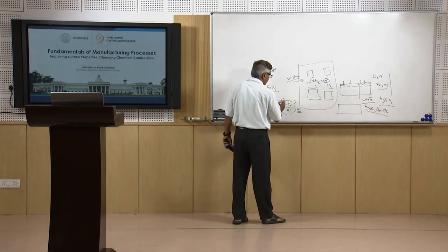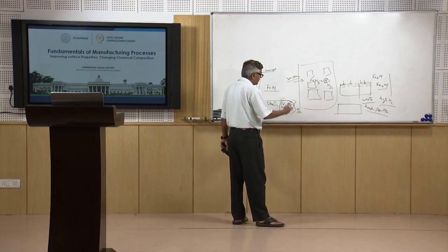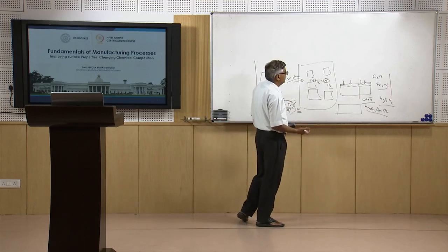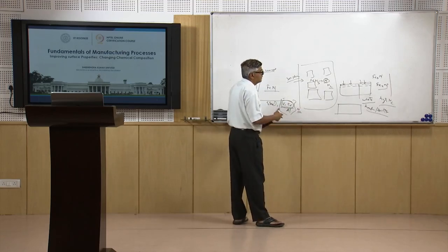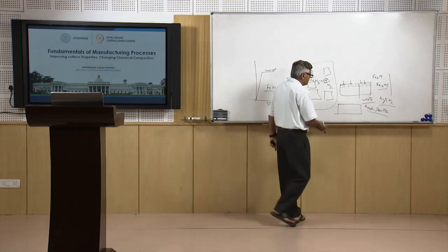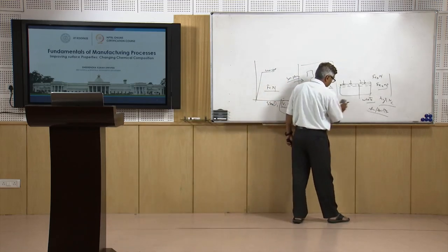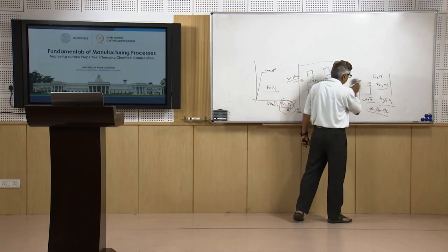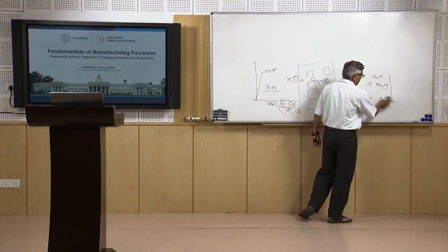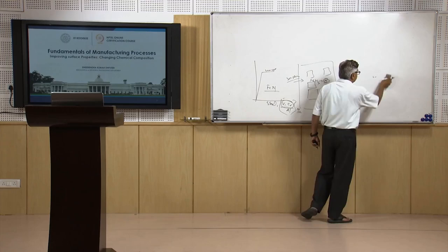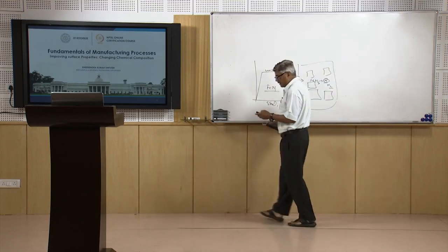These alloy steels generally have a good concentration of vanadium and chromium, because their nitrides are very hard and stable. So they will lead to a more improved and effective nitriding process, and the resulting properties will also be better. So this is the general principle of the nitriding process.